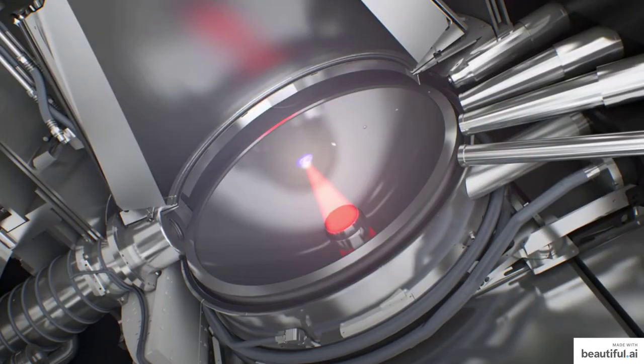Now, to produce extreme ultraviolet light, an even more ridiculous process is required than what we've already seen. Firstly, a drop of molten tin, you can see a couple there, are dropped into a vacuum at 70 meters per second. Now they're about 25 micrometers in diameter. They're then flattened into a flat kind of pancake shape by a laser, and then they're vaporized by an industrial megawatt laser amplified 10,000 times. And it's this tin plasma which releases the extreme ultraviolet light. This specific process is repeated 50,000 times every second to produce enough light for the lithography process.